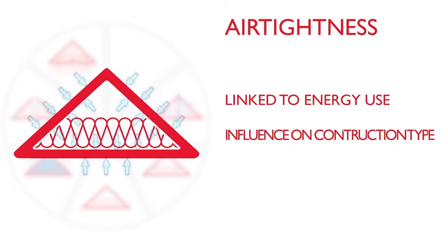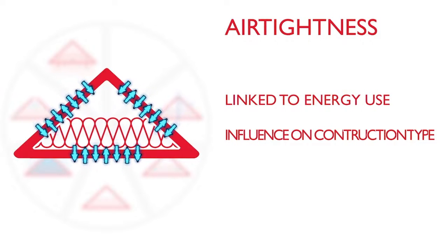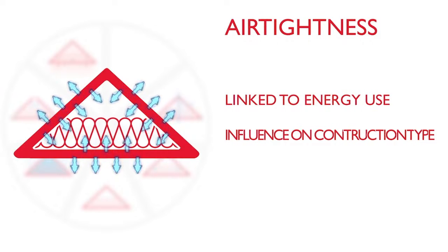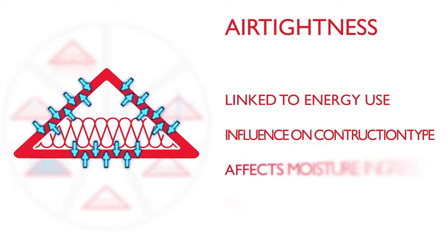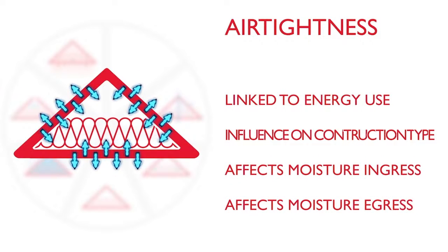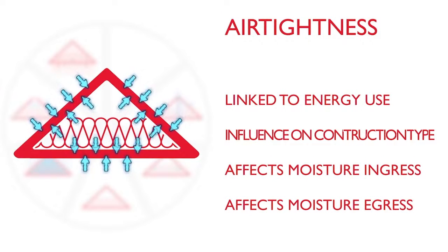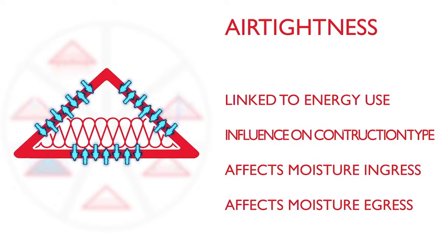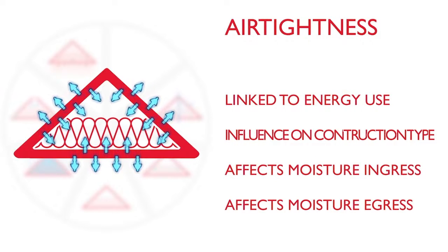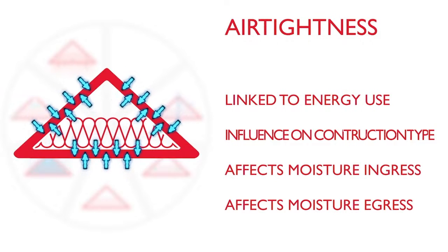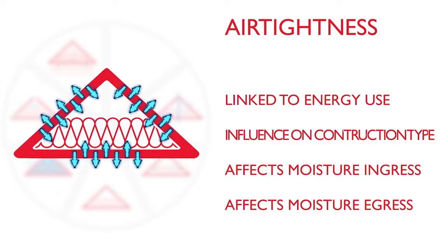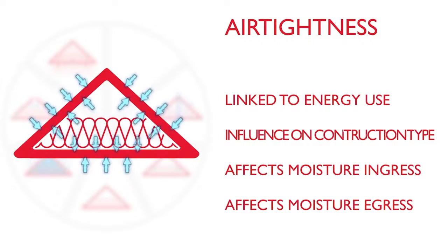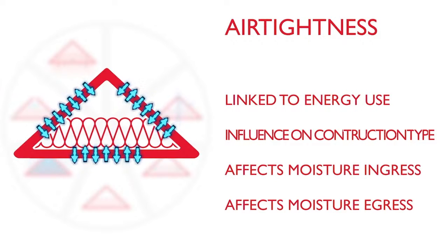Some types of roof can achieve lower air leakage rates more easily, particularly if extremely low air leakage rates such as those found in passive homes are required. Ensuring the transfer of warmer, more humid internal air is limited is also important, as air leakage can transfer moisture directly into colder areas, leading to localised moisture and condensation. Similarly, the air permeability of the outer covering must be considered, as roofs with continuous coverings such as metal sheets will have significantly different hygrothermal performance from discontinuous roof coverings like tiles or slates.